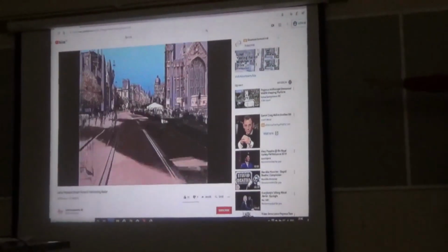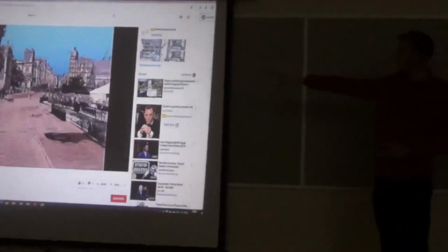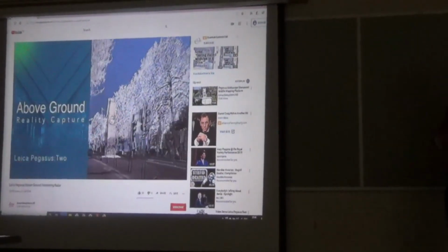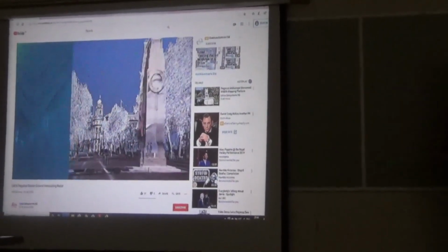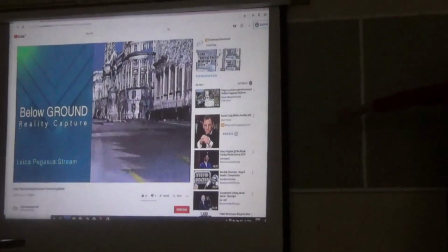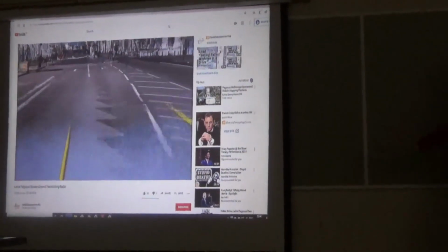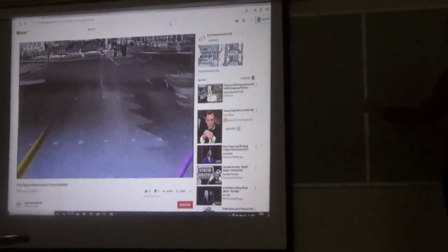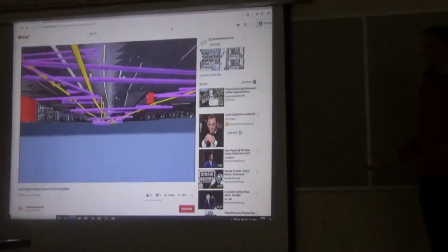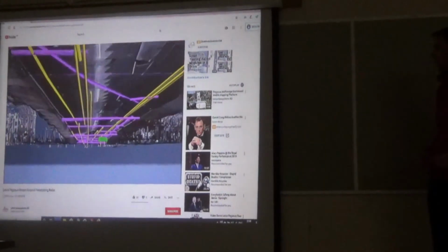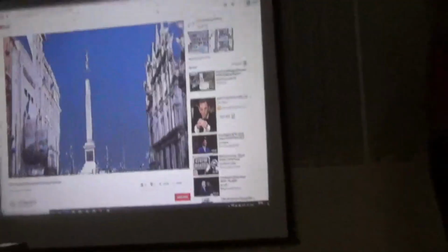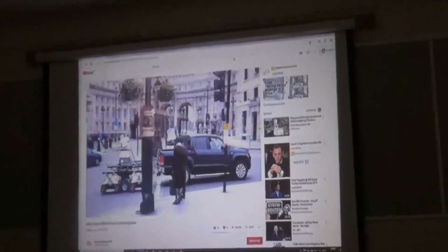So you've got a 3D laser scanner on top, producing 3D laser scanning imaging of the centre of London, not closing roads, producing this high quality 3D mapping data, but you're also producing what's on the ground, in this case buried surfaces and utilities, but that could be walls. This has all been done at road speed, not needing to close roads or dig any holes, being able to map the urban environment and where it relates to each other.